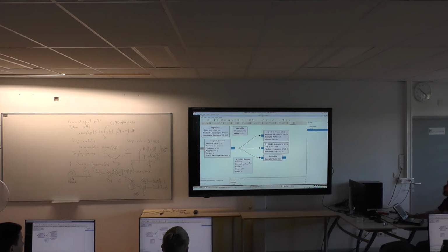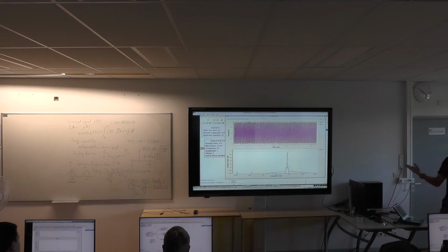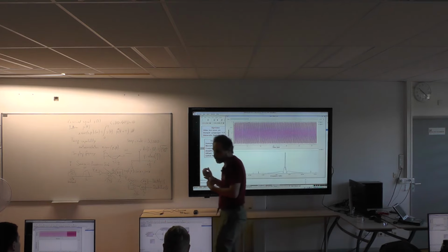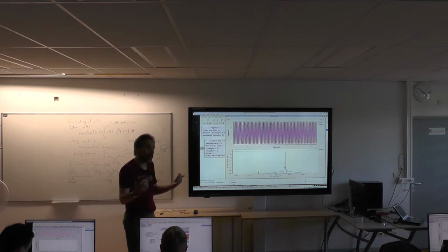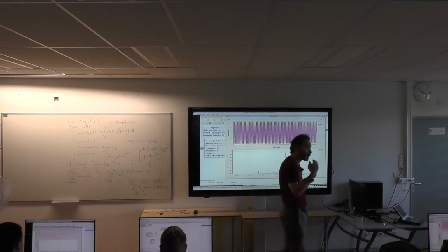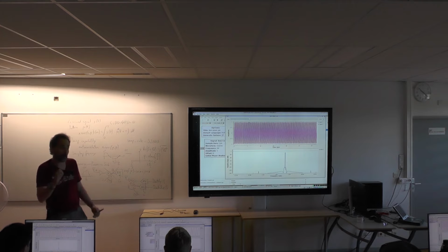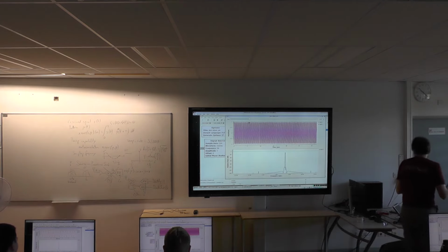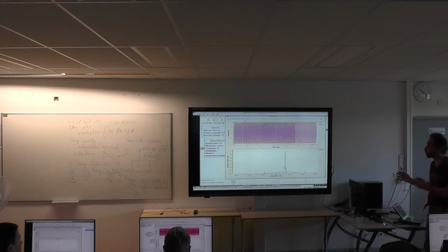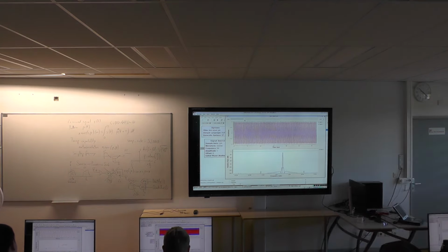And so the fun thing, and the reason why GNU Radio is so much superior to MATLAB when you want to do some signal processing, is that now I can interactively play with my flowchart, and I can change the parameters of the flowchart. This might look more like fun, but for example, when I'm receiving a satellite signal, and I need to tune a few parameters such as a loop bandwidth or a gain, if I hear the satellite signal or if I see a constellation plot and I see that the constellation is not well tracked, I can interactively play with my flowchart as the data are streamed, the IQ stream collected by the software-defined radio receiver, and I watch the output on the screen. So this interaction with your flowchart is useful whenever you want to tune the parameters of a flowchart when you're receiving a signal.